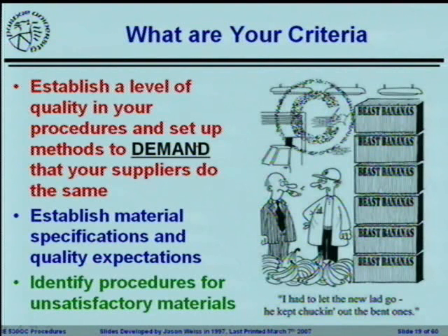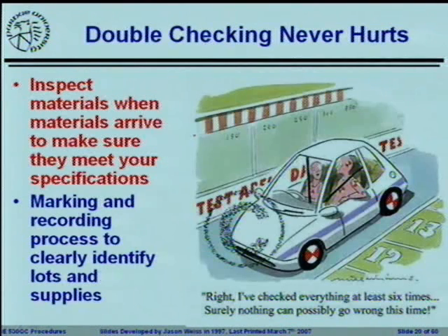Is it just good enough that they hit the ASTM numbers, or do you have other things that you want them to hit so that you're getting the right gradation, so that you can make a concrete with the right strength and low standard deviations, low variability? Make sure that you understand that if it's not hitting specification, it's going to be returned, or you've got some other policy, so that everybody's aware of it right up front.